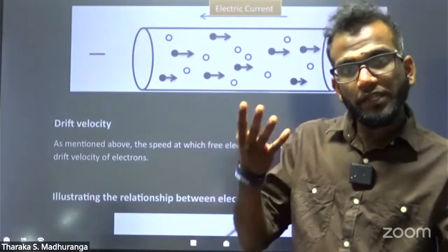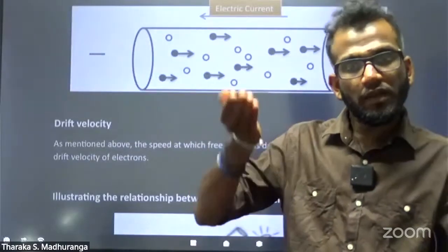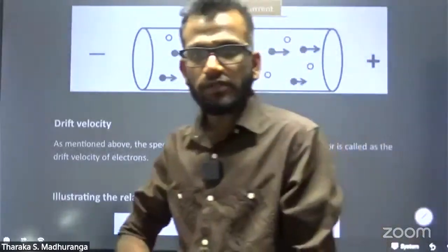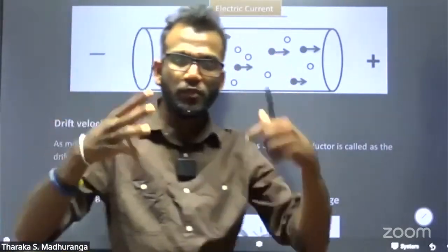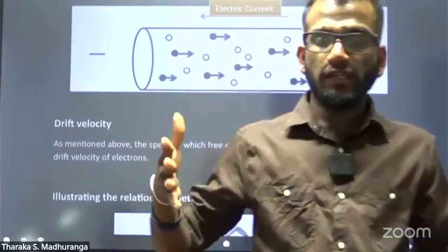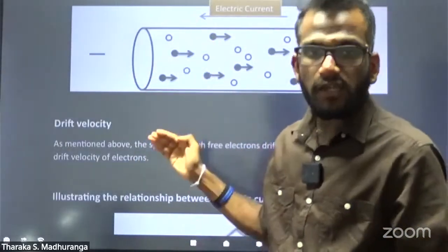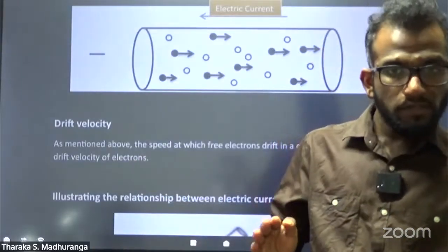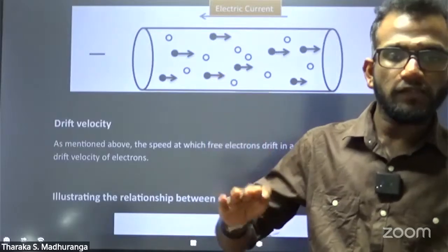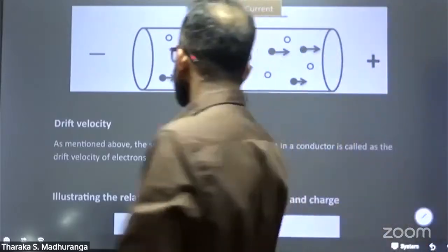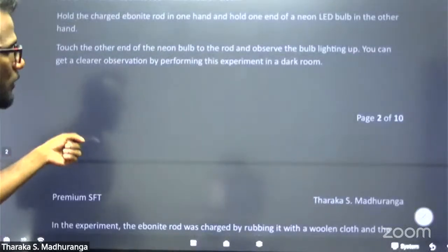Therefore, when temperature increases, the vibration increases due to the high thermal energy absorbed by the electrons. Their collisions increase, and their resistance increases. Due to high resistance, the conductivity decreases. In good conductors, when we increase the temperature, the conductivity decreases. Remember. Don't worry, we can discuss it again after the temperature effects in the middle of the lesson.